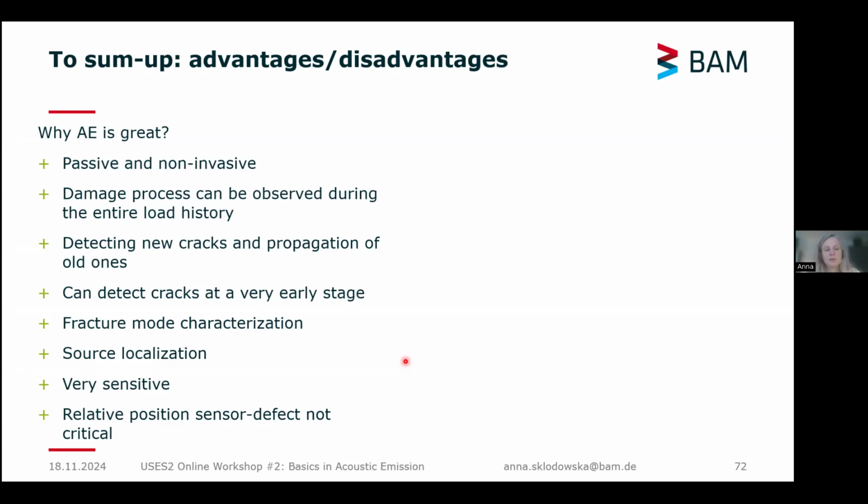It's also possible with the method to characterize the fracture mode, estimate the source location, and as I mentioned before, it's very sensitive, so we can detect even very tiny events inside the material. What is also quite nice, compared for example to ultrasonic methods, is that the relative position of the sensor and defect is not critical in this case.